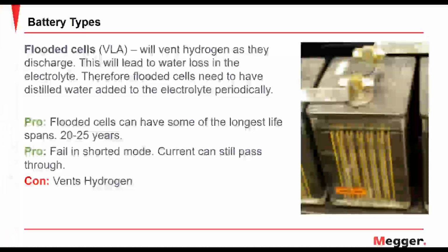The only con for them is that they vent hydrogen, and this does lead to exhausting the water content in the electrolyte of these batteries. Thus, they require distilled water to be added periodically, and thus their maintenance is quite extensive. But they last a long life.